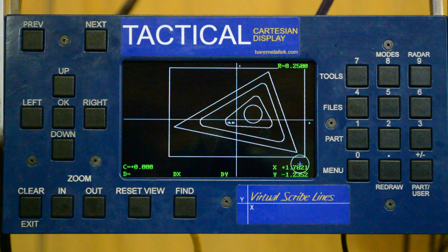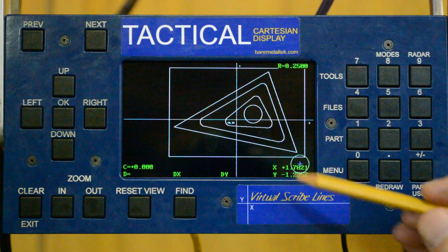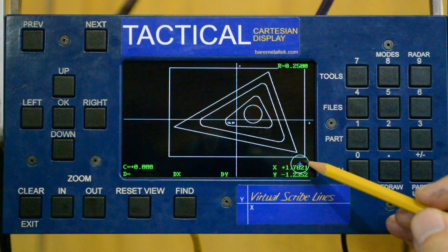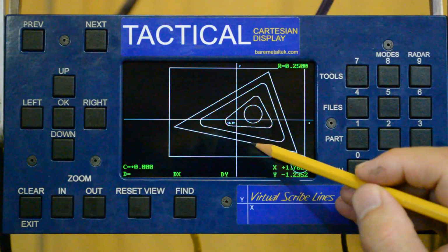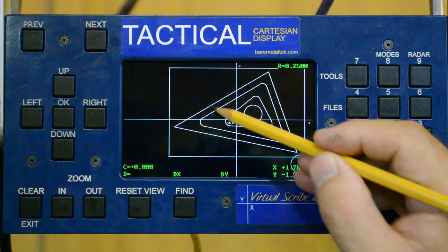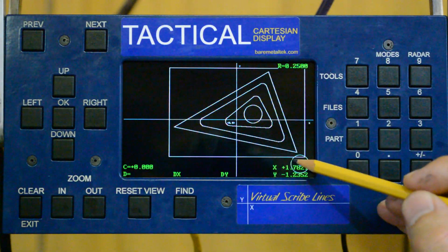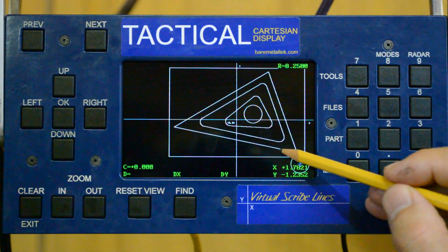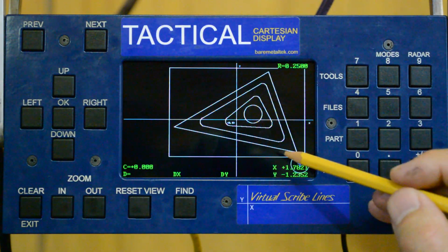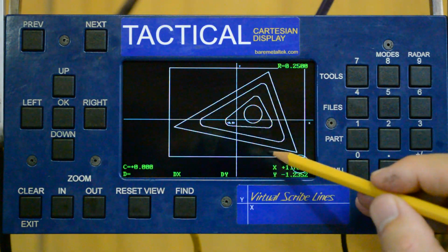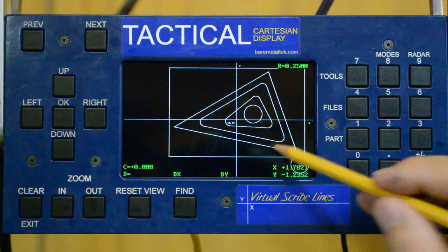Okay, a little about the machining strategy I'm going to use here. I'm going to machine with a 1/2" end mill around the perimeter of this triangle, and what I'm going to do is put these lines parallel to the x or y axes one by one, and make several passes going down in Z until I get to the depth I want. I'll be leaving some material on each of these surfaces so that I can finish all 3 of them in the end, and I'll make 1 or 2 passes around the whole perimeter to bring in these final dimensions.